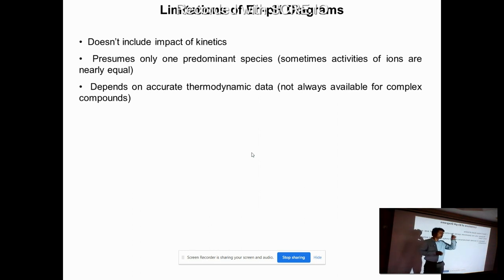If the potential and pH fall in the corrosive zone, definitely the metal ions will be stable, so oxidation is predominant. If we are falling in the passivity zone, what is the meaning of this passivity zone? Where metal oxide is stable. So definitely a metal oxide will form, which always tries to not allow the oxygen to interact with the fresh surface. So what will happen? Your corrosion is prevented by forming the oxide layer. So oxide layer formation will be in the second zone.